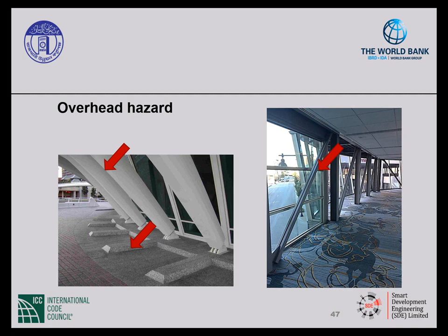And as that cross bracing comes all the way down to the floor, you know that there's going to be a portion of that that is under 2,000 millimeters. Now, while this is not directly in the path of travel, someone who is walking down this corridor that may list off to one side could easily run into this and injure themselves.